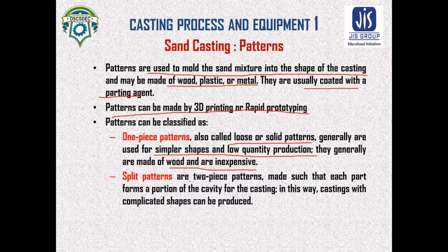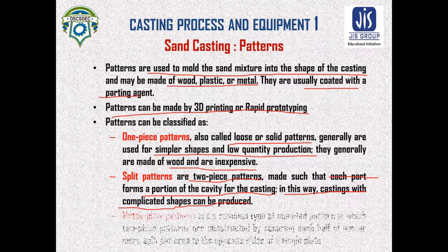When patterns are made in two pieces, then it is called split pattern. So when they are split patterns, they are made in such a way that each part forms a portion of cavity for the casting. So using split pattern, casting with complicated shape can be produced.